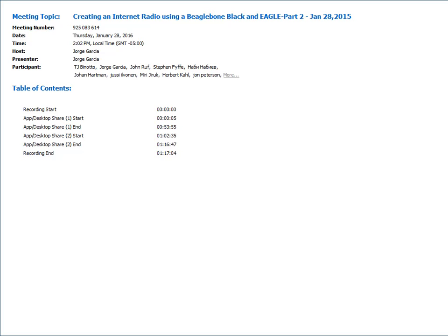Okay, so here we go. There's a question. How can I edit the property of a group of vias at the same time? I can group move or group copy, but not group property. The way you do that is by using the change command. Let's say for example you want to change the diameter of all of them. Then you would form a group with the vias. You would go to the change command, select diameter, select what diameter you want it to have, and then you would apply that to the group by either right-click and selecting Change Group, or just holding Control and then right-clicking on the group. That'll work just as well. Okay, hopefully that answers the question, NK.